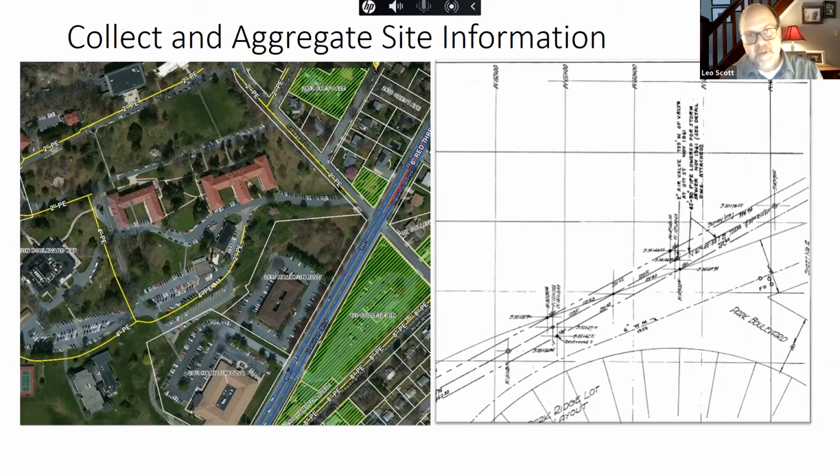While on the right side, we received PDF and paper files from a water and wastewater utility that we had to literally bring into the GIS. We brought the image in, aligned it, and then we had to trace over those lines of the pipelines and draw in the manholes and the valves, and then manually type in the data associated with those features. So you can see different levels of complexity with each one of these data systems that we're putting in. From here, we generated a GIS base map that was utilized to go into the field.